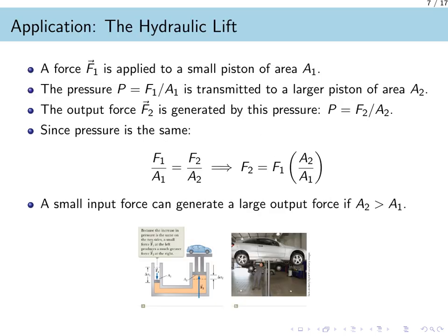A classic and powerful application of Pascal's law is the hydraulic lift, which allows us to multiply an applied force. Let us see how this works. We start by applying an input force, which we call F1, to a piston with a small surface area, A1. This action creates a pressure within the enclosed, incompressible fluid. This pressure, P, is equal to the force F1 divided by the area A1.